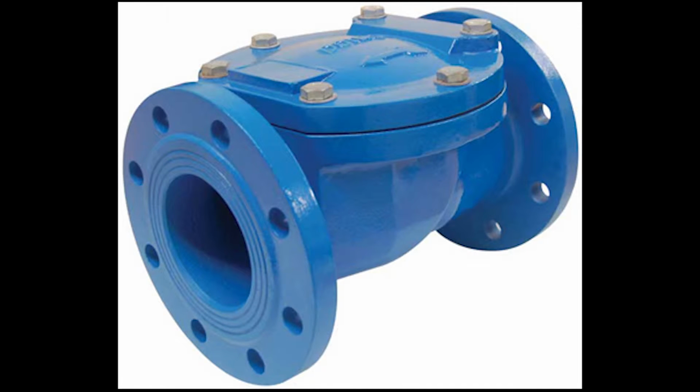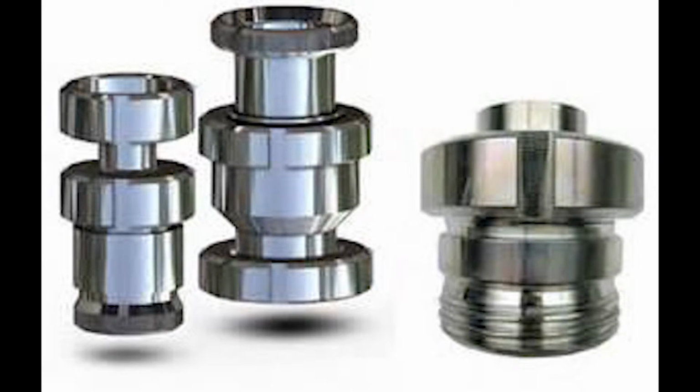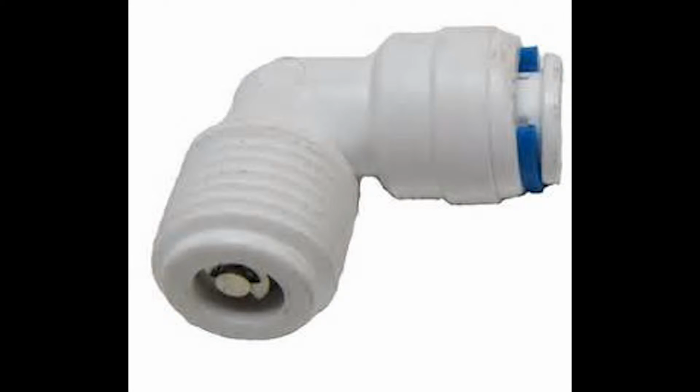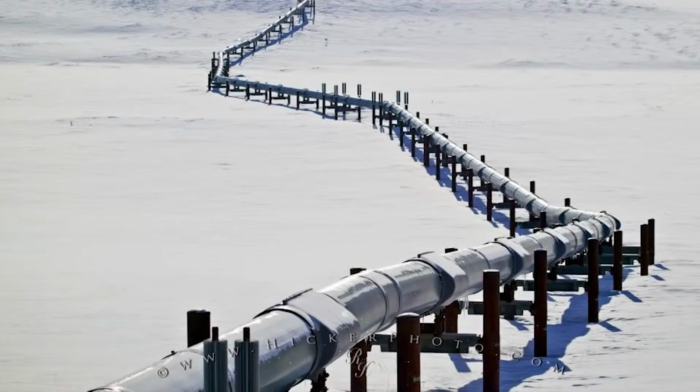Non-return valves come in many forms. They work by allowing flow in one direction but not the other. Fluid can flow only one way and any backflow will shut the valve. They cannot be directly opened or closed, but they are useful when implemented as a safety precaution for flow. Non-return valves are mainly used to protect pumps and compressors, so they have many applications in most industries, such as water treatment and petrol production.